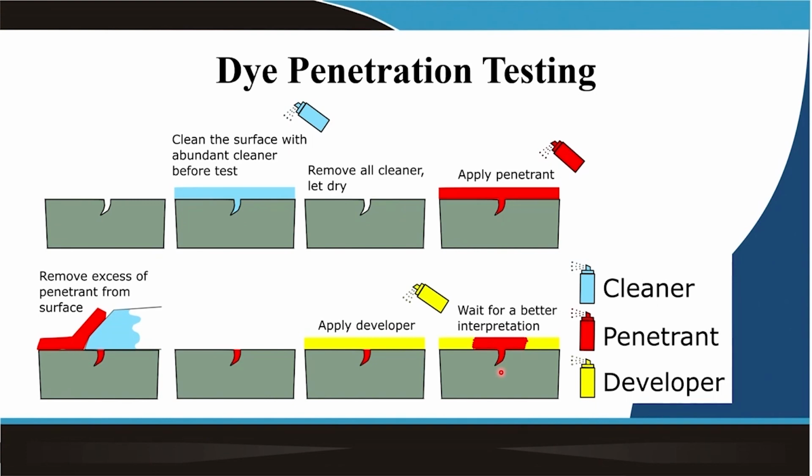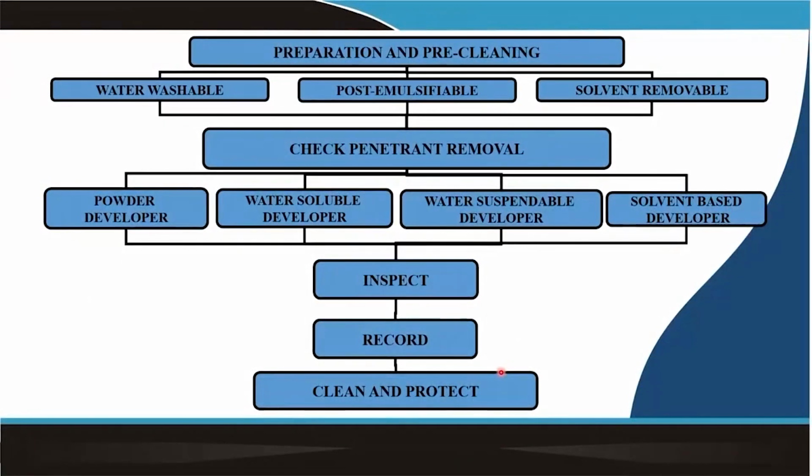This dye penetrant test is a very easy technique. As a result, it can be applied after any surface processing, like surface melting, surface alloying, or surface hardening. After that you clean the surface, or apply any coating, and do the dye penetrant test, and you find out whether it is defect free or whether defects are there on the surface.